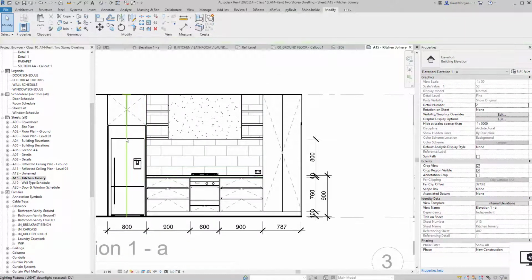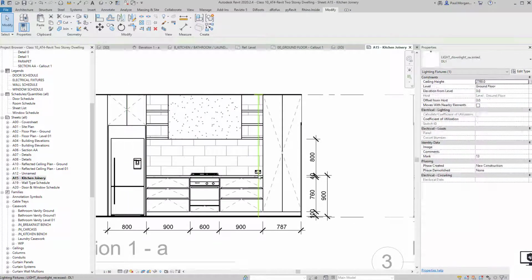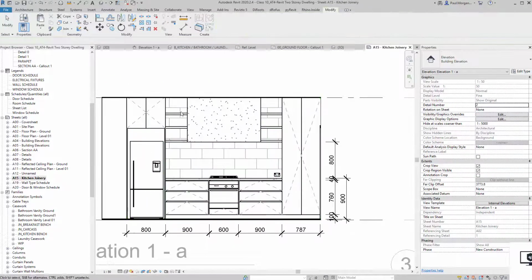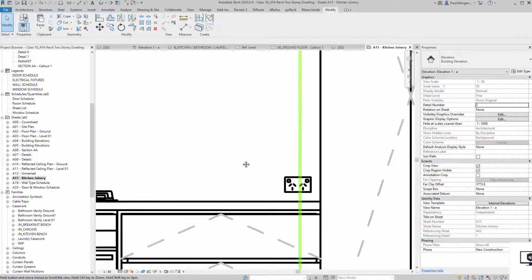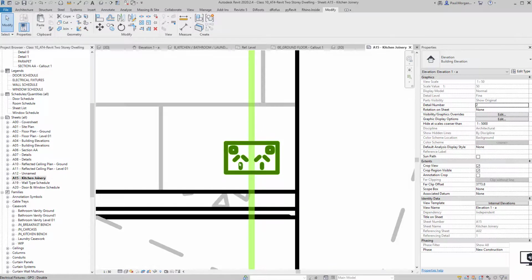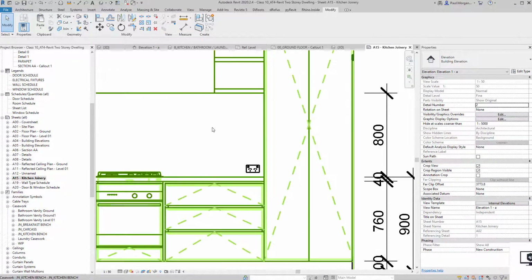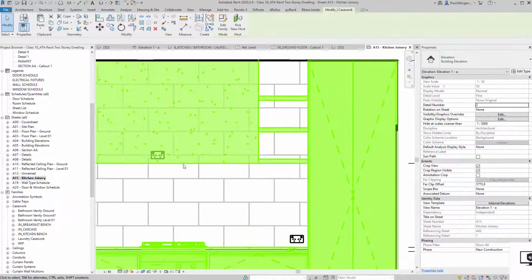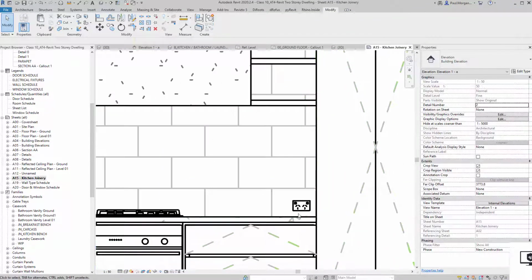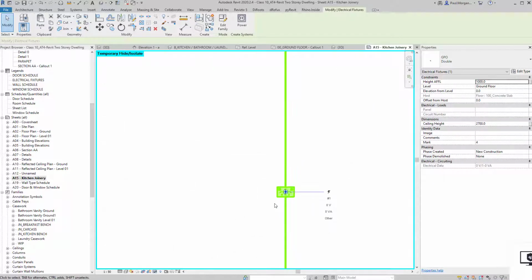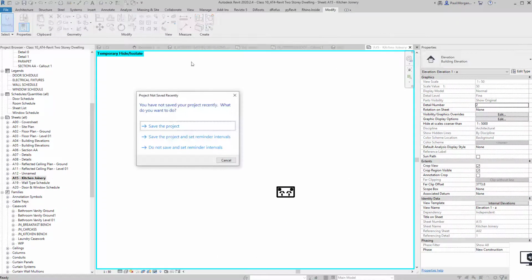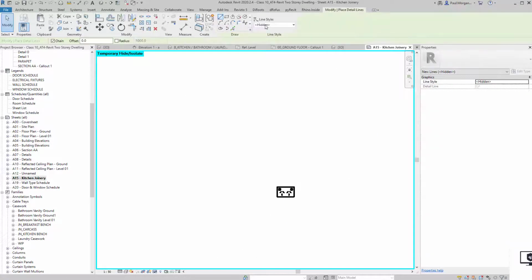and some detail components as well. So inside of some of these models, to give an example, the GPO just here, we can draw a GPO and then place that over the top of where the real GPO is behind. So what I'll do is I'm going to click on this GPO and go HI to isolate it. I'm going to grab a detail line, and I'm just going to use my pen 1, and I'm just going to trace over this just roughly.